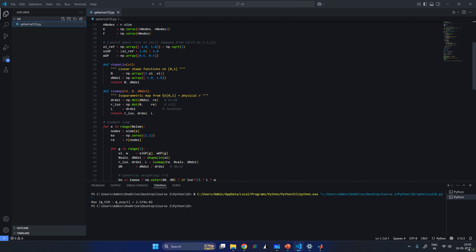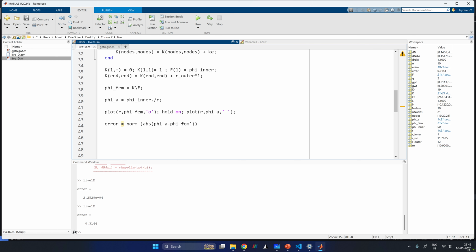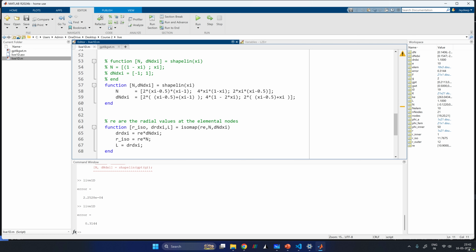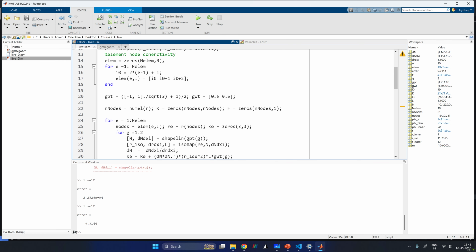So this is how we code the finite elements, and you will see that when we go to higher order elements, you have already seen it's very easy to just modify the code. Almost nothing has changed in the basic code structure. We just changed the shape library, right? If we want, we just have to change the Gauss points, which are just here. The Gauss points are Gauss rules. So you can just run this from 1 to num Gauss, right? So it's very simple to crank up the order.